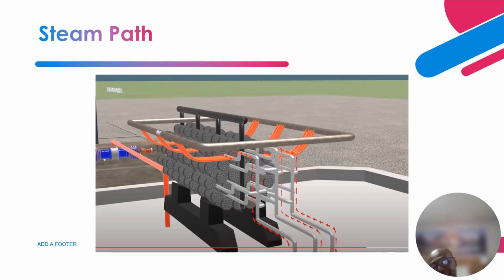This is the steam part. You have a fuel assembly, shown over here, and like I told you, it has a closed loop water system that flows through the fuel assembly while the nuclear fission reaction is taking place. The water takes the thermal energy from the nuclear fission reaction through conduction and creates a steam path that flows to a steam generator, to create more steam and get a drier steam before it is transferred to the steam turbine.